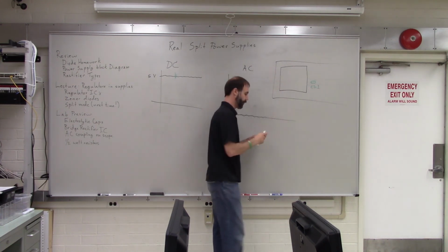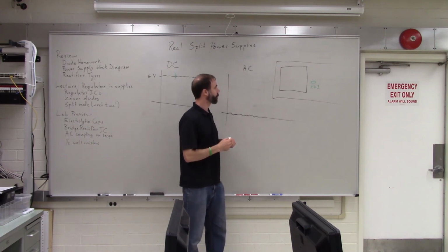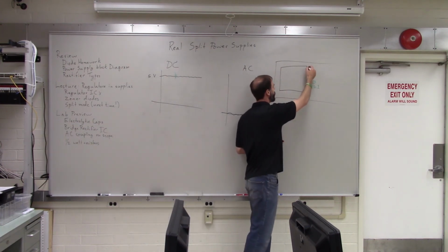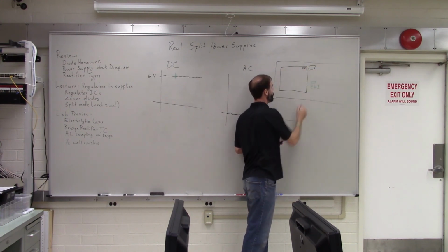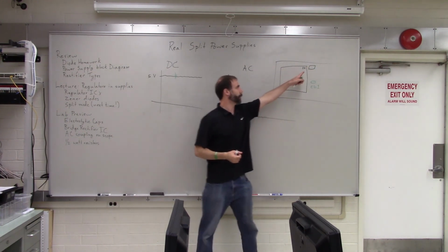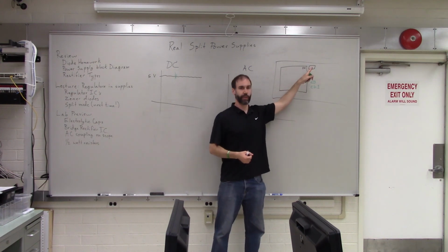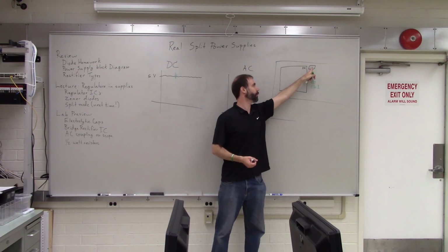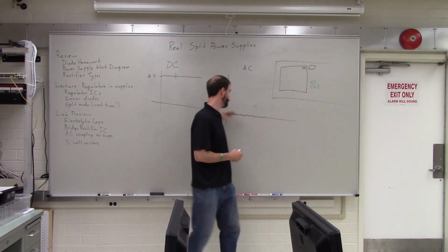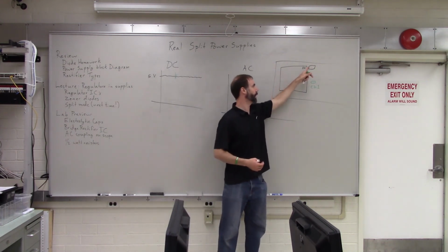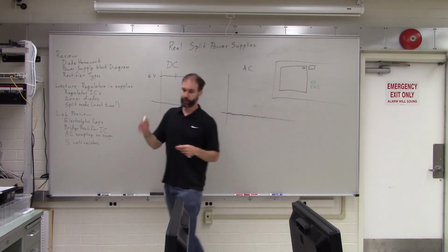So you would push channel 1, and then up here, it would say DC, and there's a little button next to there. If you push that button, it cycles through the different types of coupling. It starts out in DC, you push it, it goes to AC, and you push it again, and it goes to ground, which just gives you a flat signal. And you push it again, and it cycles back through DC, and so on and so forth.